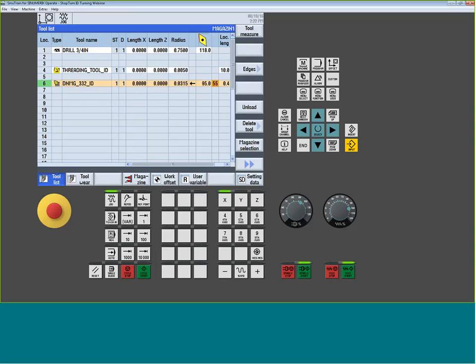You see how the insert picture starts to tip. Let's make it a little more dramatic. See how the tool starts to rotate. Same scenario, if I go less than 90, it rotates the other direction. So it's the same concept as the OD tool. It's going to automatically be inverse. So you don't have to change your numbers at all. If I look at my catalog, or I go back to that image and it shows me I got a 5-degree relief, I can just add it to the 90, and there's our orientation.